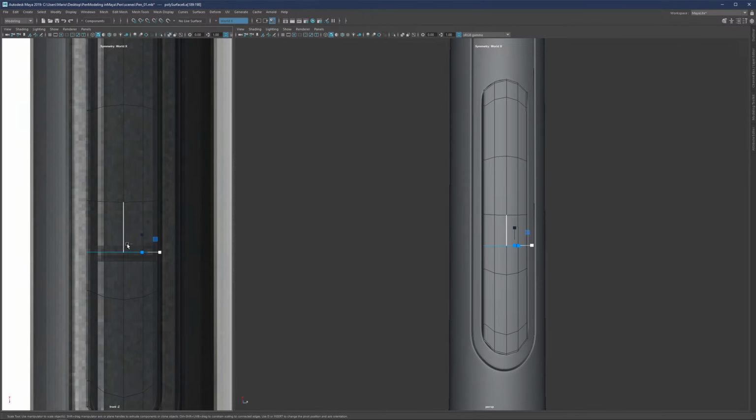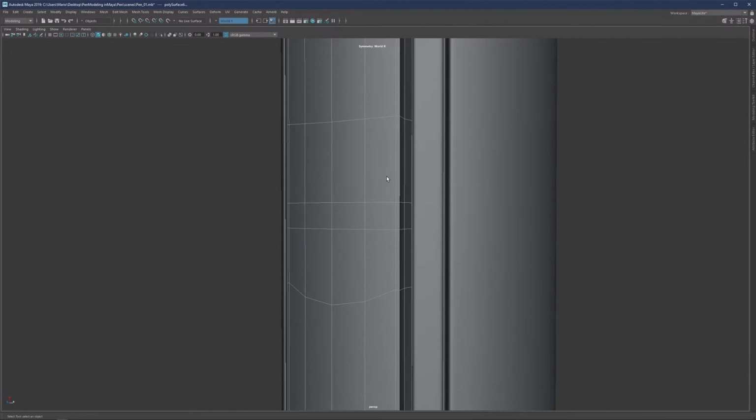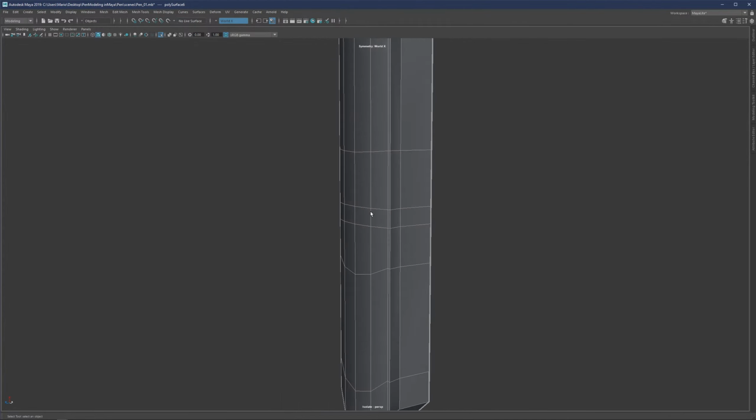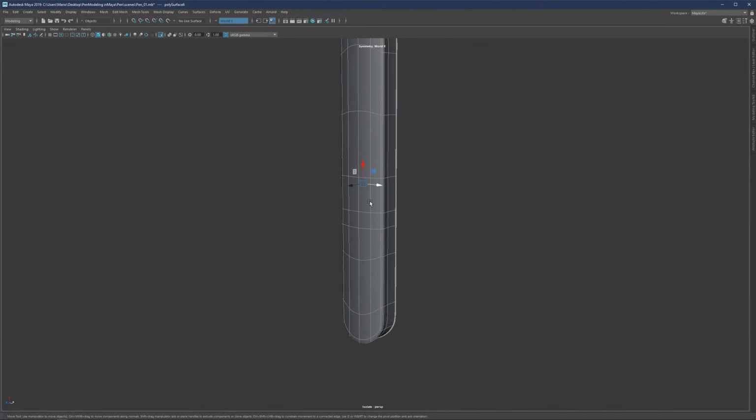And what we can do is now use bevel. All right. Hit Q to confirm, and let's select it, Control 1 to isolate, and now we can work on it as a standalone object. Here I don't like how this turned out to be, so let me do one more extrusion like so.